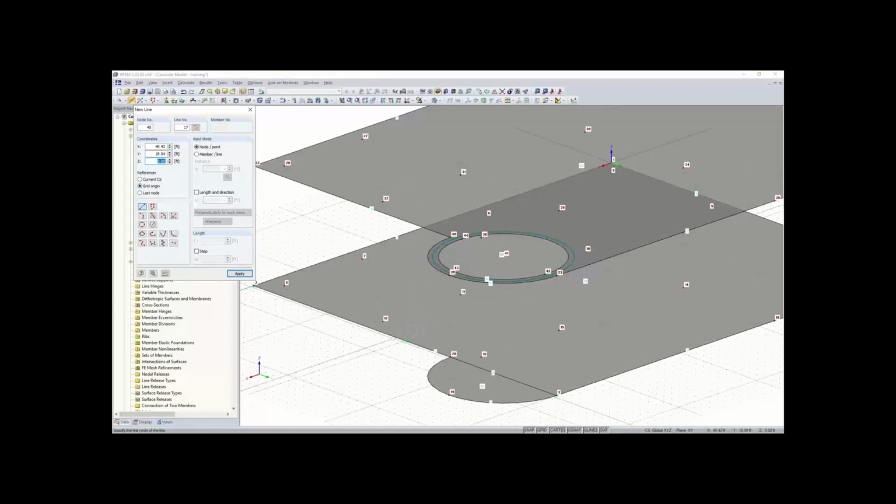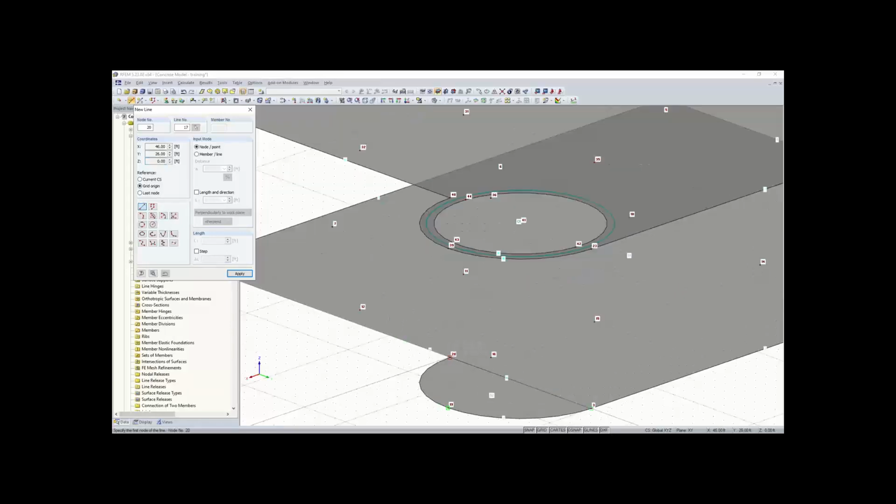as our wall boundary. And this is going to be, let's see, about 7 feet away from node 20 here. So that will be at 4619. So we'll go to 4619. I'll draw up to the line, and again, you get that nice symbol there, that snap point for perpendicular, kind of like AutoCAD, and there you go.